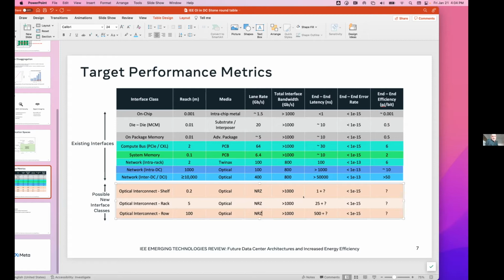That's a fairly profound implication, as you pointed out, just in VSR versus LR on an ASIC, right? Never mind different modulation. So these are now business and other issues that come in. But just from a performance standpoint, for optics, NRZ, or as Clint pointed out, if you're going to go coherent, it's QPSK. It's just overwhelmingly the best thing to do. You go to PAM4 and literally you're talking about a 3 dB hit.